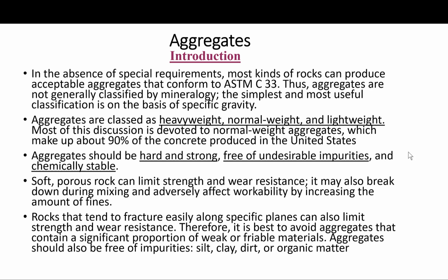Aggregates, again, just in general, should be hard and strong, free of undesirable impurities, and chemically stable. Soft, porous rock can limit the strength and wear resistance of the concrete. It may also break down during mixing, which will adversely affect workability by increasing the amount of fines and other undesirable results.